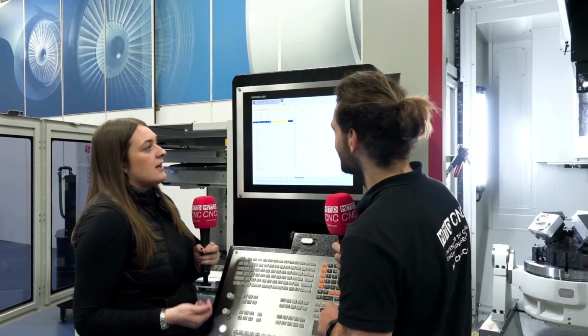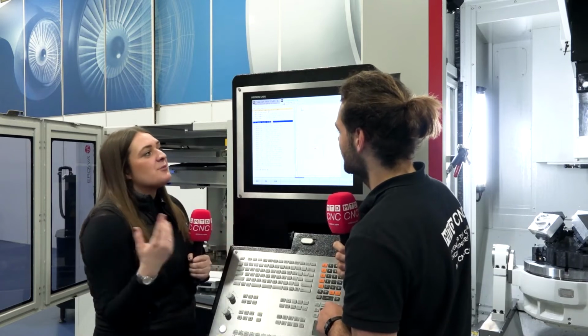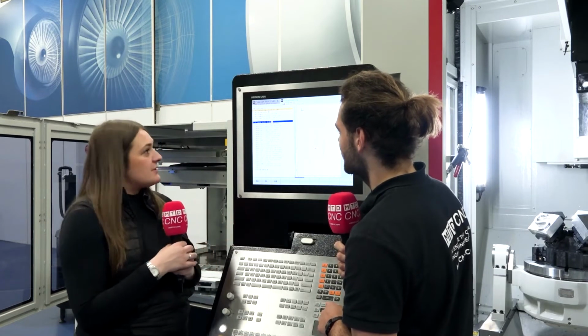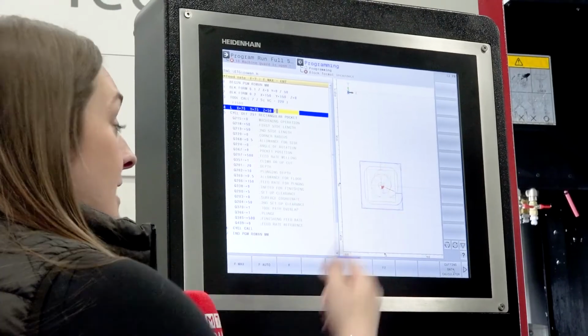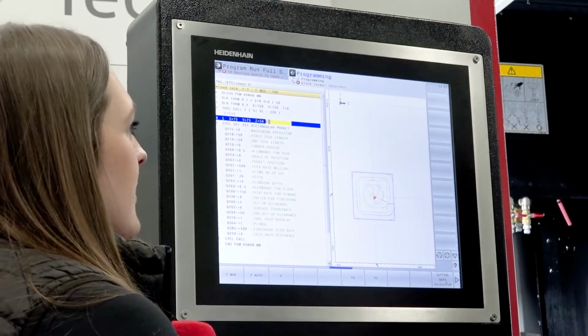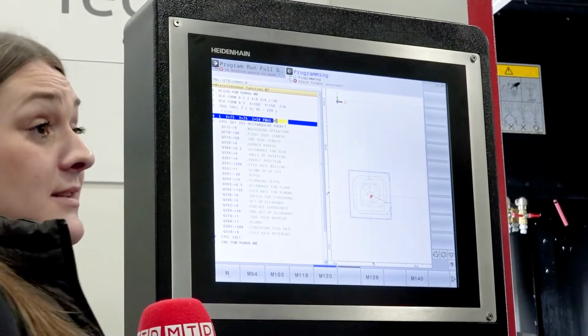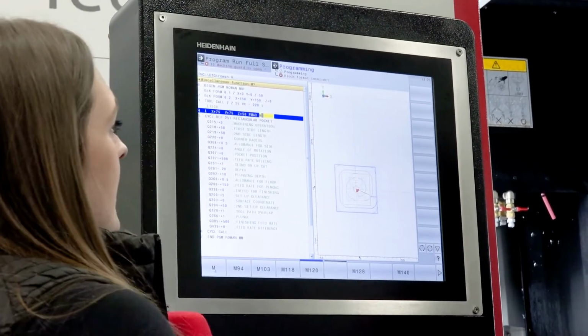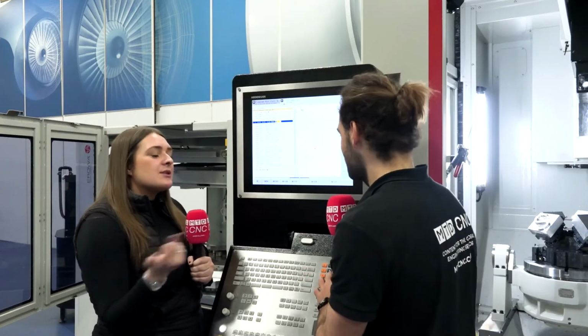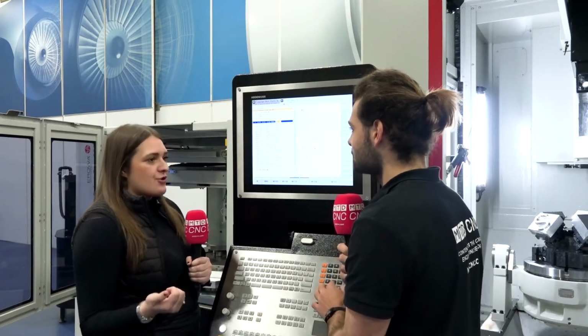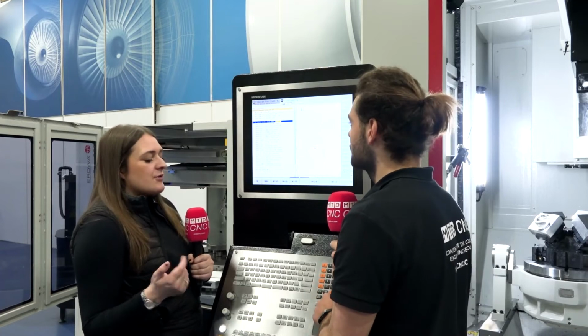Because we've got a 5 axis, we've got a B axis as well, but we don't need that. We don't need radius compensation, because the compensation comes on in the cycle. We've got a feed rate, so we can do F max, fast rapid as it's down there. Do you want to call any coolant? If we put M13, it will turn the spindle clockwise and turn the coolant on at the same time. So we press end.